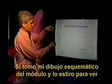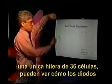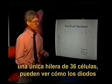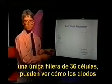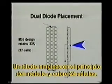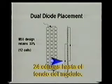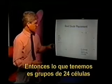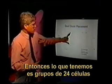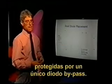If I take my schematic drawing of my module and stretch it out to show me simply a single string of 36 cells, you can see how the diodes cover the module in an overlapping way. One diode starts at the beginning of the module and covers 24 cells. The other diode starts in the middle of that group and covers the other 24 cells down to the bottom of the module. So what we have is groups of 24 cells protected by a single bypass diode.